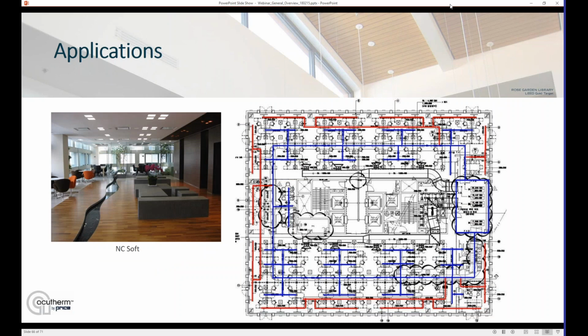Another approach here, this was a loop run around the floor, air handler per floor in this particular office building. And then that was run at all low pressure. And then some low pressure drop reheat coils used to pick up the perimeter spaces and provide that heating along the perimeter. But basically the rest of the building's a cooling zone. And again, Therma-Fuser diffusers throughout, sub-zoning that space with those individual thermostats to provide that individual control.